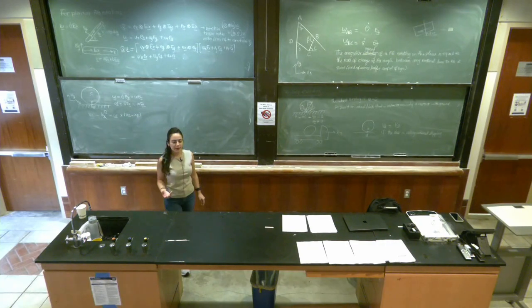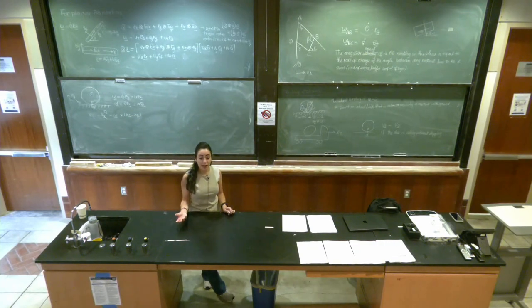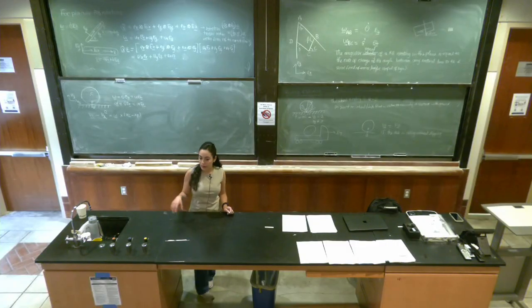What is VC? What is the direction of VC? The velocity of the center of mass. Right, it's horizontal. It's the only point on the rigid body that is moving in rectilinear motion. It's going on a straight line. All other points are going on curves.